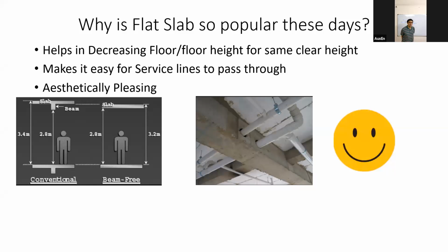Yes. So one thing is the sagging zone. At the sagging zone of your beam, let's say at the mid span, you have got your maximum sagging moment. That means you have got tension at your bottom face. So below the neutral axis, somewhere near the mid span of the beam, you may plan a sleeve, because that concrete is in the tension zone, and you can remove concrete from the tension side because steel is taking care of the tension.